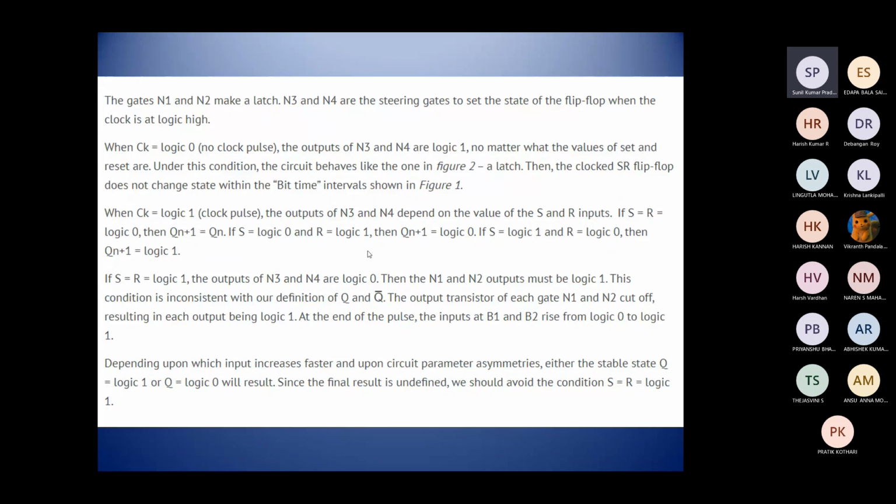So now, since the final result we can't determine, the final output is undefined. So we should avoid the condition S = R = logic 1. We should always avoid the condition where the set and reset inputs are equal to logic 1.